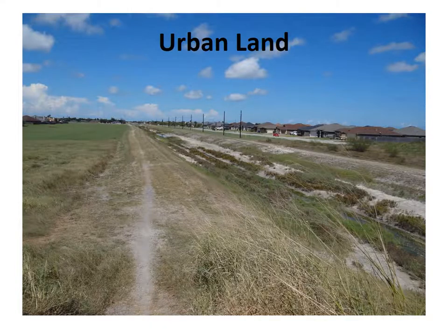In an effort to deal with erosion and increased discharge, cities often resort to alterations of the stream channel and floodplain. Where erosion is severe, hard or soft engineering solutions are often implemented. Vegetation and large wood is often removed to allow floodwaters to move through the channel faster in an effort to reduce the magnitude of flooding. However, by removing the roughness from the stream or riparian area, the energy of floodwater is increased, causing an increase in bank and channel erosion. Furthermore, when floodwater moves more rapidly through the urban areas, flooding problems farther downstream are exacerbated.